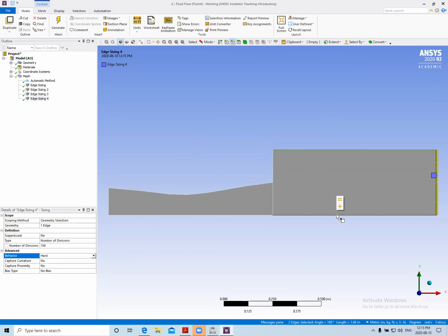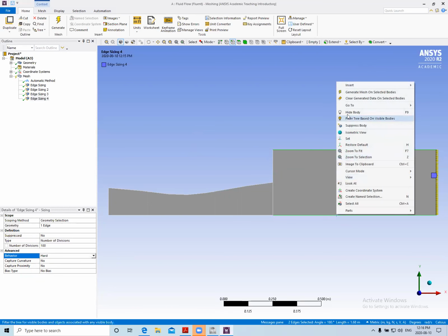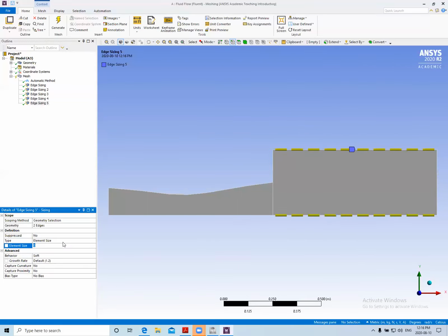All right. The mesh also for these two lines. So I'm gonna make it 200 points. And after that, I'm gonna check if the number of points I added is enough or not.